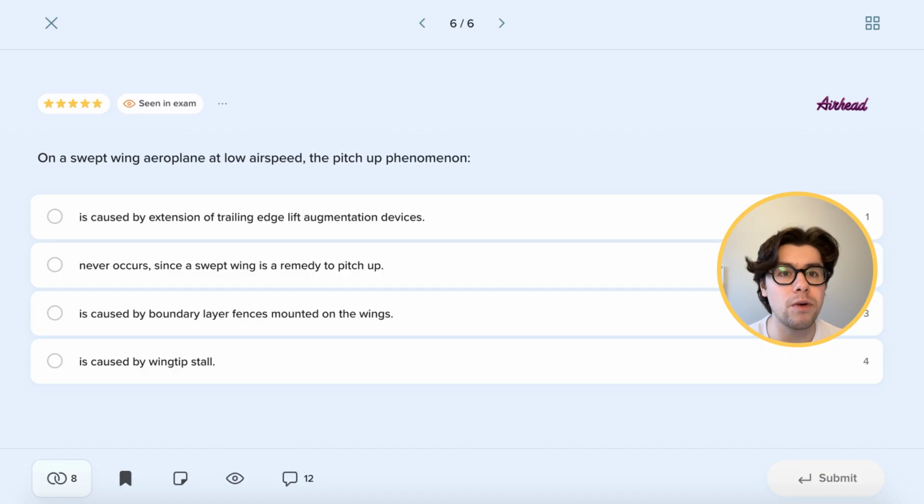So remember that the downwash will be highest at the wing root, and then it will consistently be lower at the wing tips. As the downwash is lower, the effective angle of attack will be increased. So as the effective angle of attack is increased, it means that the critical alpha will be reached sooner than at the wing roots. This in effect causes the wing tips to stall first, and because they are more aft, the center of pressure of our wing will move forward.